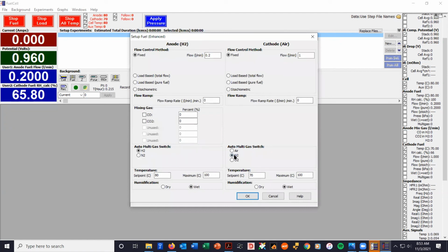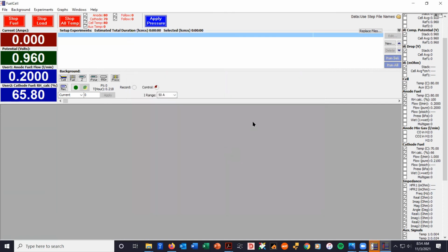We could also do EIS with the potentiostat at open circuit. Say the fuel cell is working with hydrogen and air, so it is an energy producing device. We have an open circuit of around 0.9 volts, and we want to do impedance at open circuit. We can't do it with the load, as I just mentioned, but we could do it with the potentiostat.